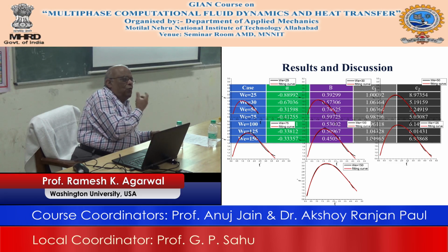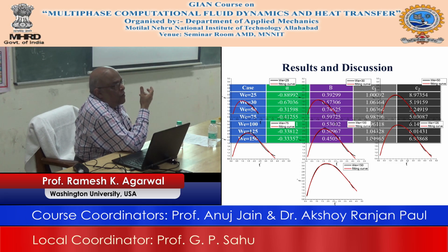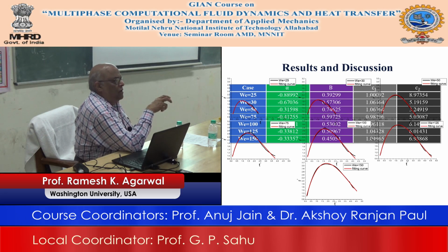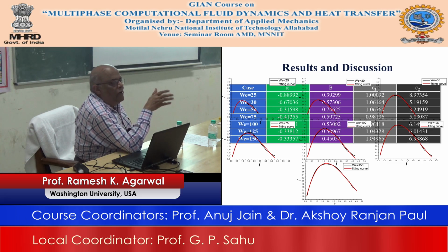So the same thing I am trying to point out in this context, that this can be very useful, because what we are doing here is that we are coming up with this dashpot for a collision of droplets, which is already existing. It is not that we have discovered this methodology ourselves, but it was already done for solid particles and it is there in Fluent, but it was not done for the liquid. So now what they have done is they took that already existing knowledge, used Fluent, got the information and created a dashpot model for the liquid particle.